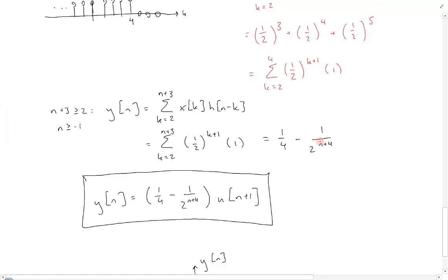Altogether, we have seen where convolution comes from and how to use it. We saw that the convolution sum is a direct consequence of the LTI property of systems and allows us to find the response of the system to any arbitrary input, all by knowing the system response to a simple delta function. This is not generally true for non-LTI systems and is the reason that LTI systems are so good for analysis.